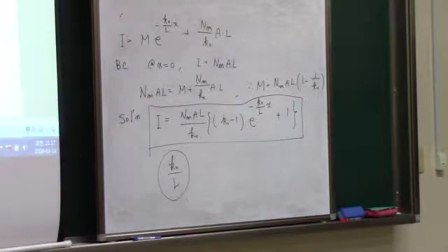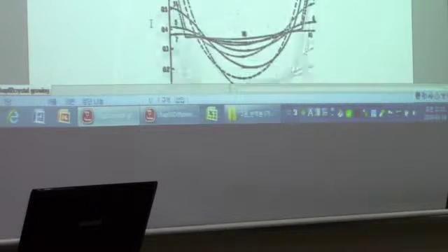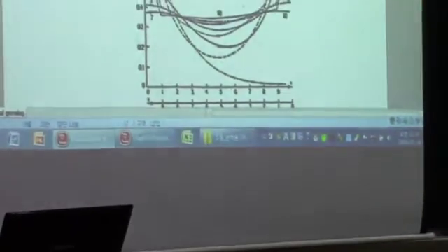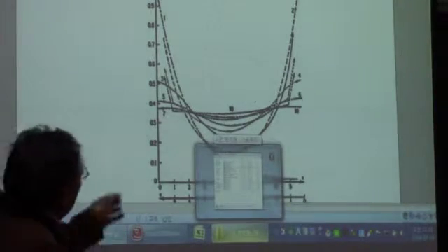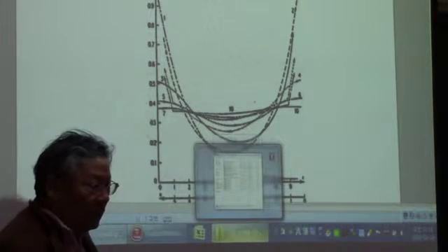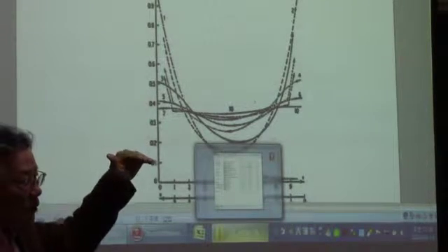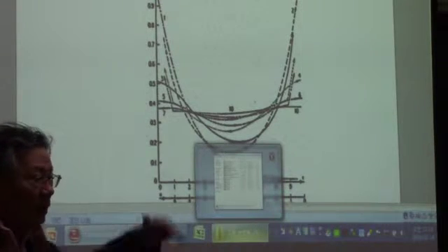and this is a computer simulation of the dopant. No, this is the Czochralski one. This is the float zone technique for dopant distribution, and the numbers you can see in this figure are the number of passes of the molten zone. In a float zone technique, you can move the molten zone in the up direction, and then go down and up and down.